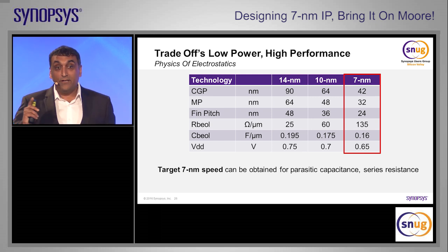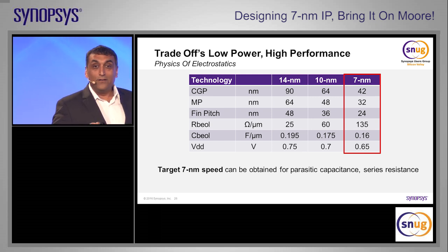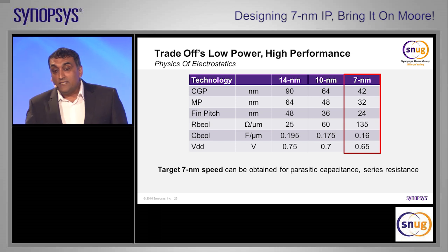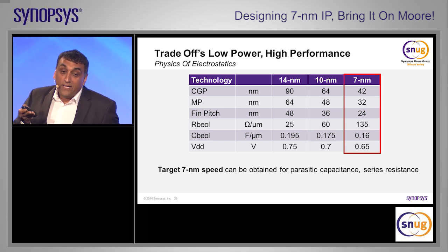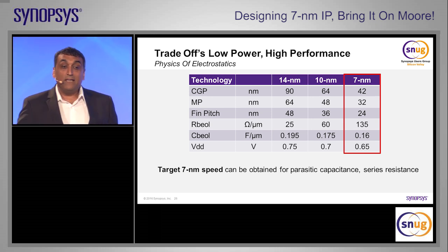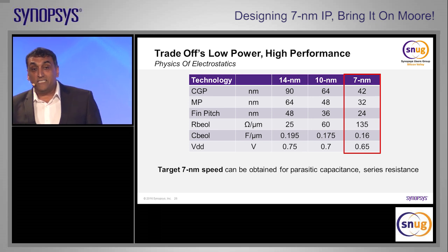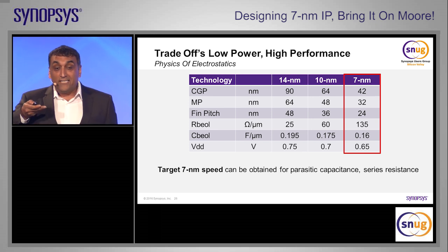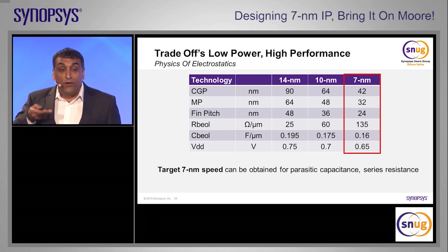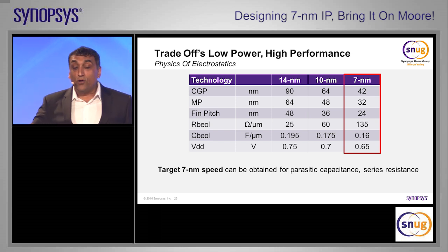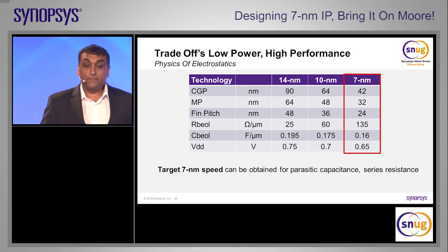Okay? If that's complete gobbledygook to you, basically what I'm saying is that those 2 parameters give you a good switch. Okay? The sub-threshold slope represents the behavior of the switch in weak inversion, and the drain-induced barrier lowering represents the electrostatic behavior of that switch due to a drain bias when the threshold voltage starts to vary.